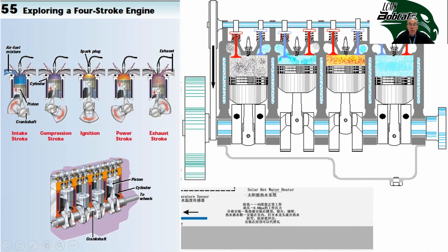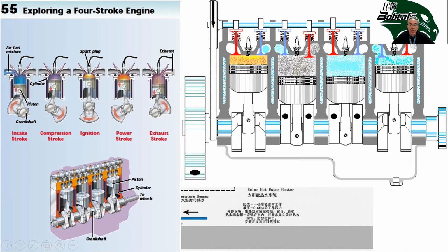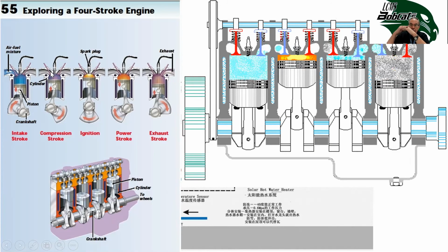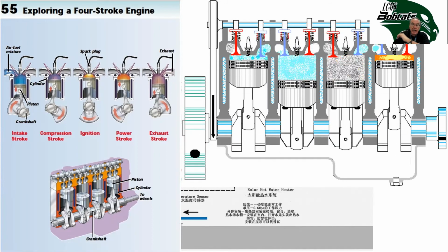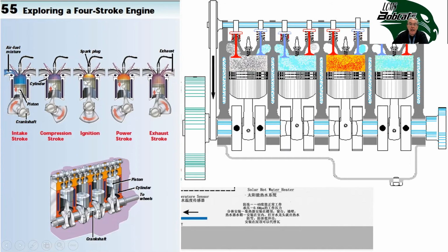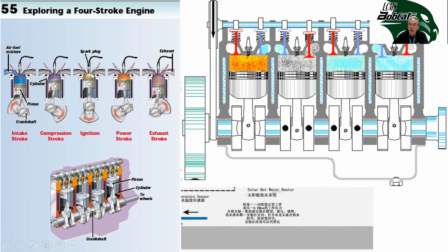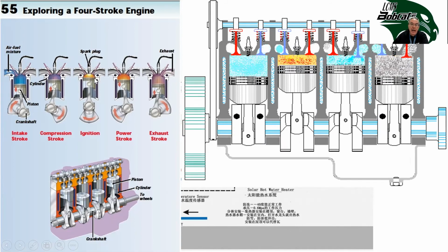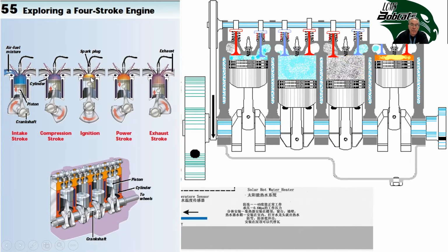If the spark plug went off now, nothing would happen because the piston's already at the bottom of the cylinder. So the next stroke that happens is the piston goes back up, both of the valves are closed, and it squeezes the gas and air into a really small space. That's called compression. And last year we learned that chemical reactions usually don't happen on their own. So the spark plug provides activation energy and starts an explosion. The gas and the air burn.